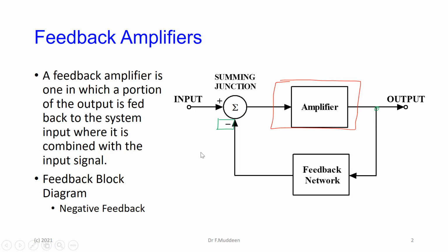And remember what negative feedback does when we were talking about controls. With negative feedback, you are subtracting some part of the output from the input. In other words, if the output went in some direction that you didn't want, you take some of that and subtract it from the input, so that you change the input in such a way as to bring the output back to where you want it.